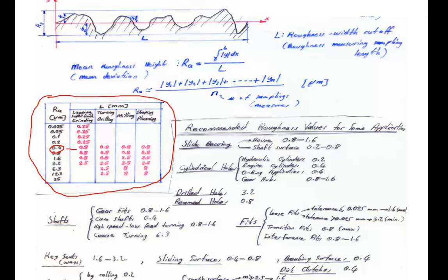Well, make a guess. Having a look at the quality of the surface, say something on its quality. Say that roughness is in the order of 0.4 or 0.8. Make such a guess, and then measure the roughness size.